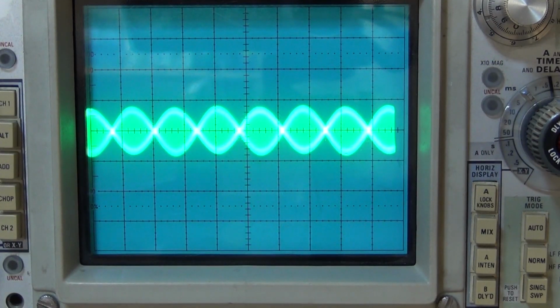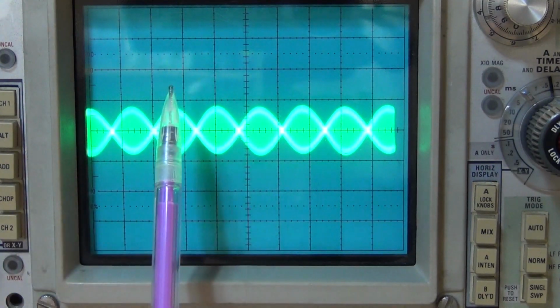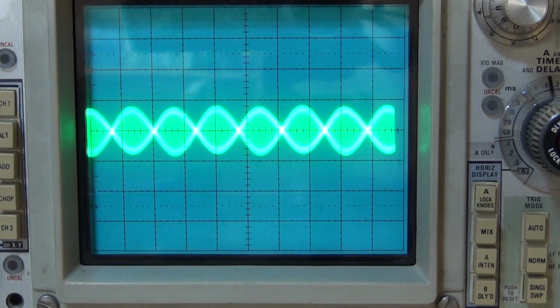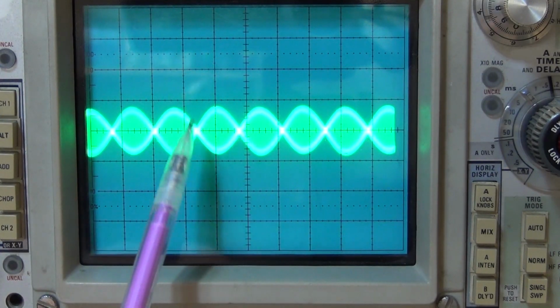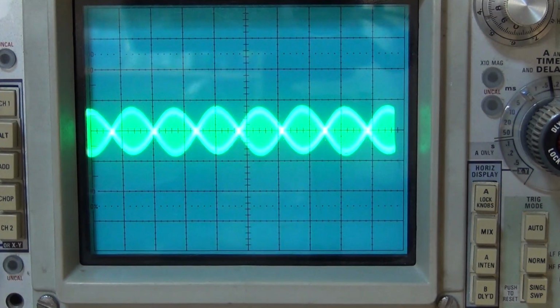But most importantly, we can see what that peak voltage is. And going back to my design specs for this, I was trying to hit minus 20 dBm coming out of the balance modulator. That works out to 31.6 millivolts peak going into a 50 ohm load, and you can see with each division here about 50 millivolts. That's awfully close, if not a little bit more than 30 millivolts. So that means it looks like everything's working fine.